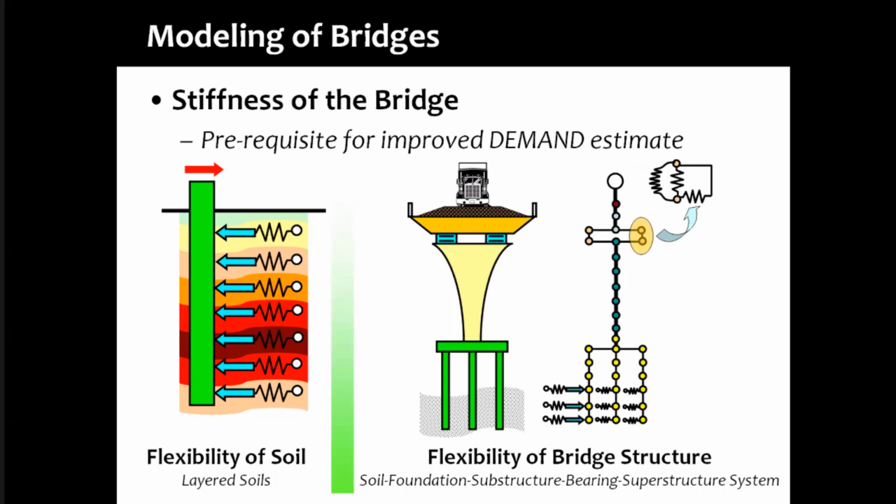So if you have to learn one lesson from seismic design of bridges, you learn the first one, which is that vertical members will see the damage. The second one is that you have to model soil and all the components of the bridge, do a free vibration analysis and obtain the natural period from there. That is what you will see as your primary responsibility.